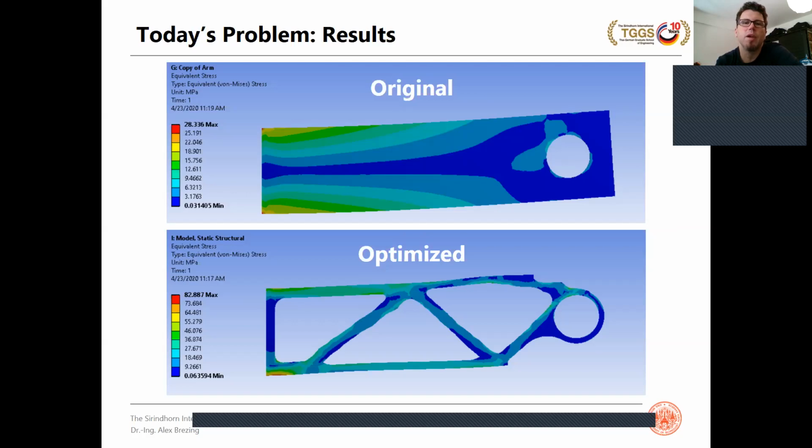Basically, the first step, you will run a regular linear static structural analysis as a bending beam. You will see, you can already estimate how this thing will react. You will see what stresses and deformations will result with the unshaped geometry. And then after the optimization, you will get a pretty interesting shape. I have to say, it's basically a two-dimensional case.